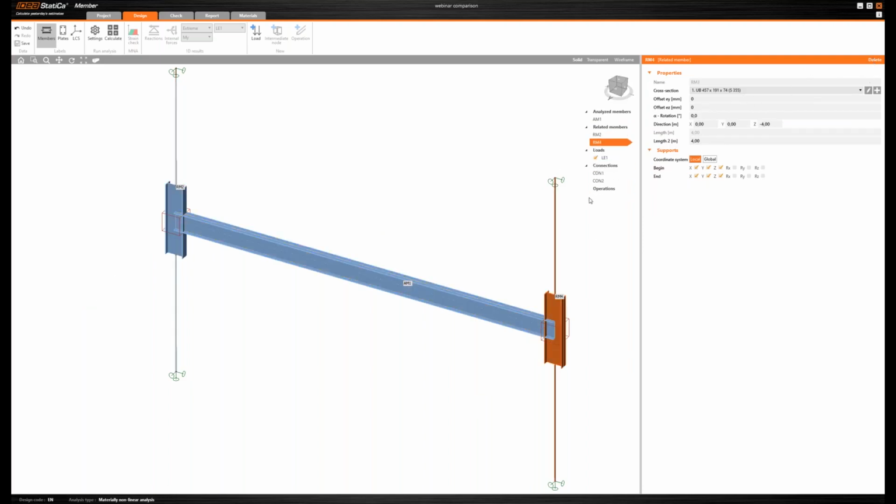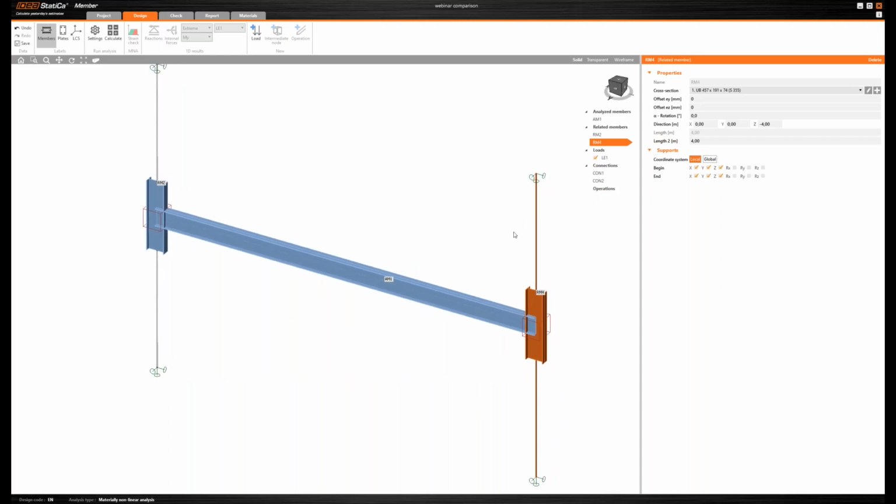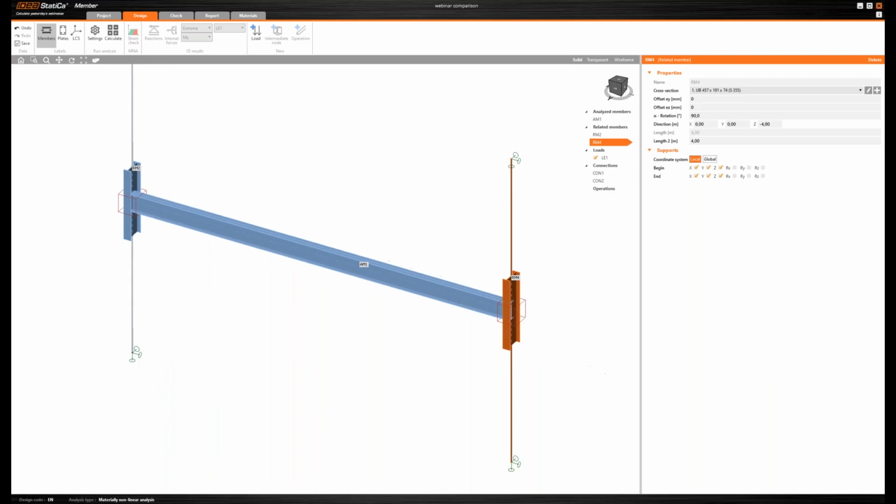So this beam, and since this beam is hinged, I will also rotate the columns so that it is connected on the weak direction of the I sections. Another important aspect of this model is that the supporting members are also partially connected, and in that way, we're able to reproduce the influence of the member and their connection. In an actual project, we could potentially load these members along the height and even at their ends to approximate as close as possible the stress state of the global analysis model where this submodel belongs.